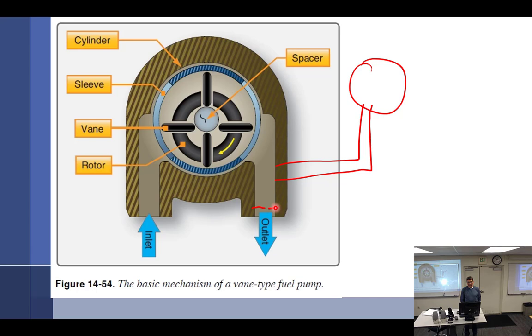As I make that orifice smaller and smaller and smaller, what happens to the flow? Goes down. The volume. Constant displacement. Constant displacement pump. How are you going to make it go down? Doesn't. So pressure goes up and volume stays the same with this drawing the way it is, because the pump's got to pump. And it's going to pump the same amount every single revolution. So if I make that orifice smaller and smaller, how much comes out? The same. It has to, or it's going to break.